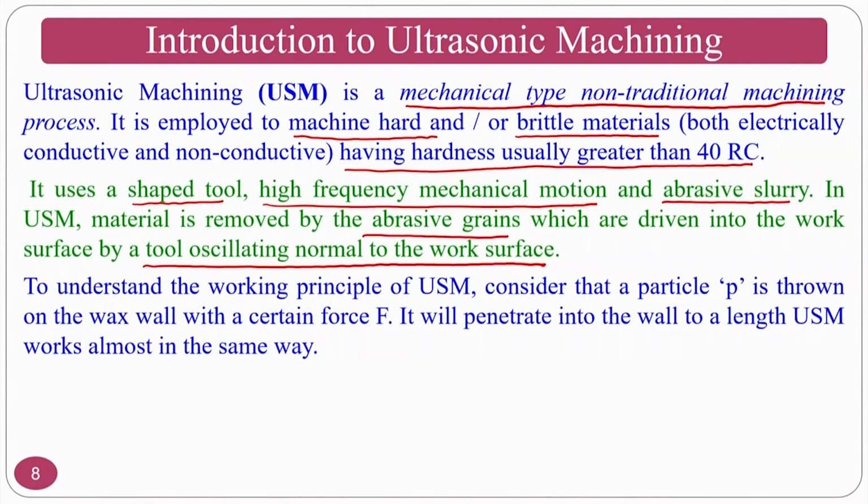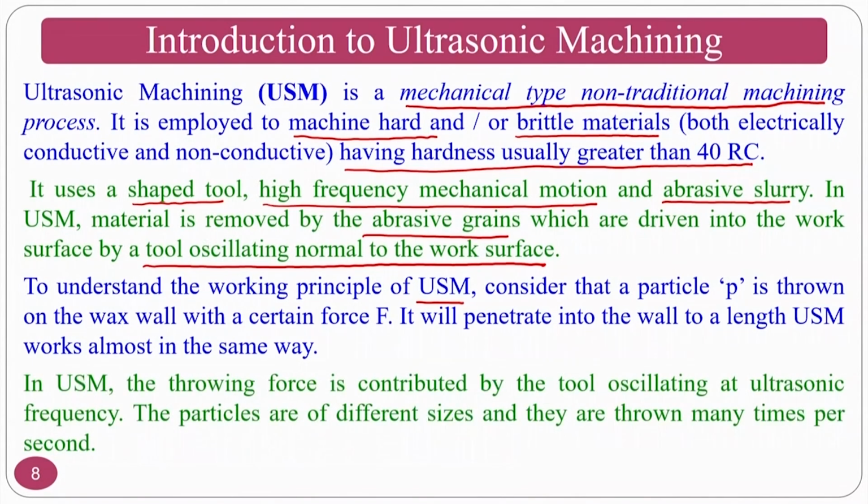To understand the working principle of ultrasonic machining, consider a particle P thrown into a wax wall at a certain force F. It will penetrate into the wall to a length, and USM works in a similar way. So, the throwing force is contributed by the tool oscillating. What it means is, there is a wax wall, you just throw a stone or a particle P, what will happen? It will go and indent into the wall.